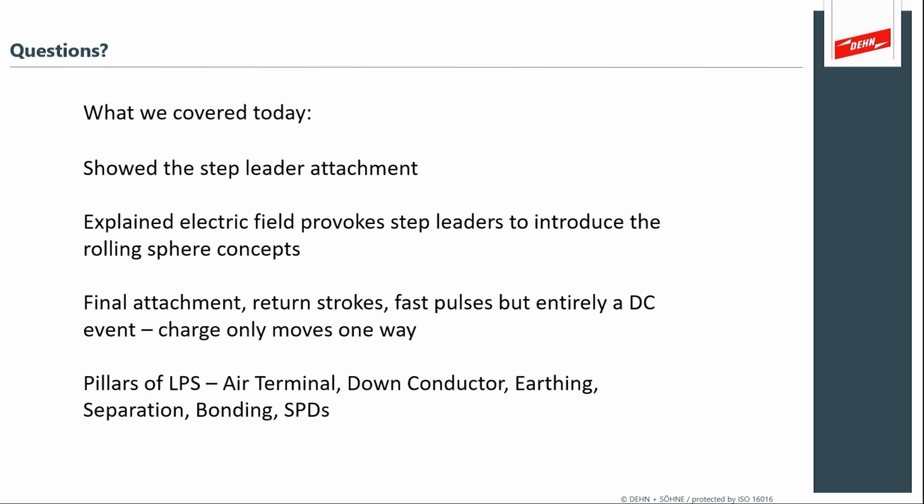Well, there are some really great publications with research done by Dr. Uman, Dr. Martin and Dr. Anton Raykov, and basically they've determined that an ESE device offers essentially the same performance as an air terminal. It doesn't provide a greater radius of protection. It doesn't do anything more than act essentially like a lightning rod.